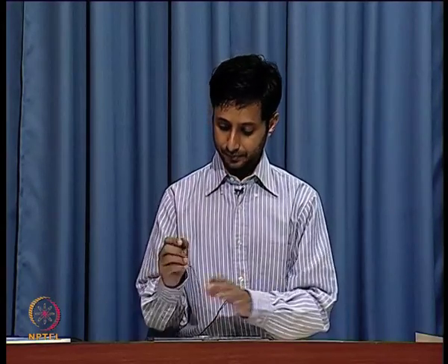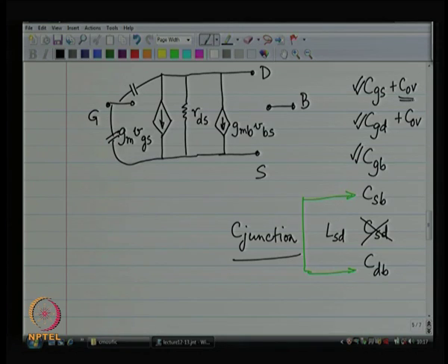In addition to what we had evaluated, there will also be a small component called the overlap. That is intrinsic to the MOSFET, because the gate overlaps with the source a little bit. So, you know the gate is like this and the source comes a little bit underneath. This region of overlap causes an overlap capacitance and that cannot be avoided, right.